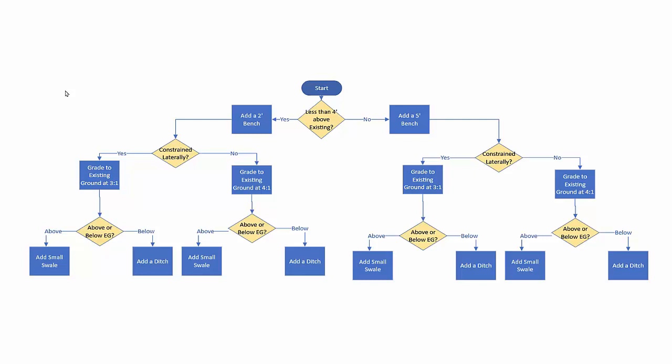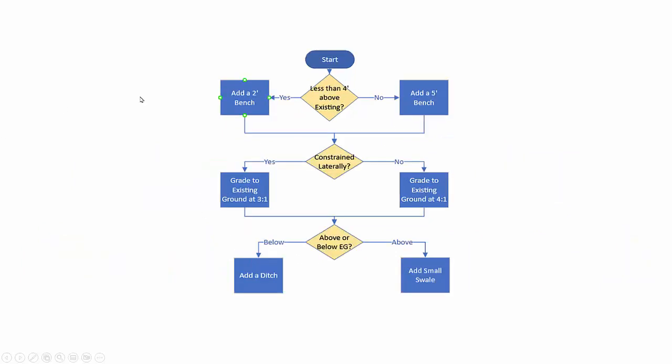I've seen these a lot. I've opened up subassemblies before where people have just hundreds of branches spread out. It's almost impossible for them to be able to track anything down. If it builds weird inside of Civil 3D, it's very difficult to troubleshoot. So this is the issue that we're trying to solve. It happens a lot. There's not a lot of great examples for it. What we want is we want all of these to come back together. So we still want to be able to use multiple conditionals throughout, but we want them to come back together afterwards.